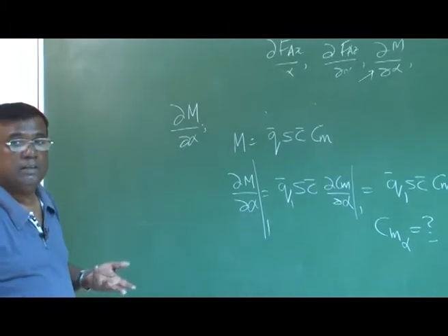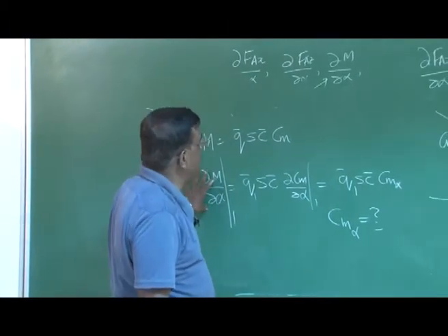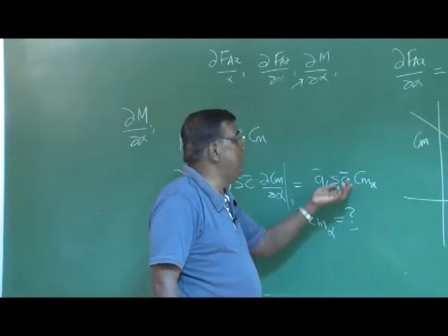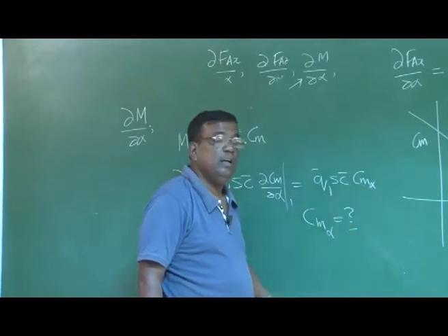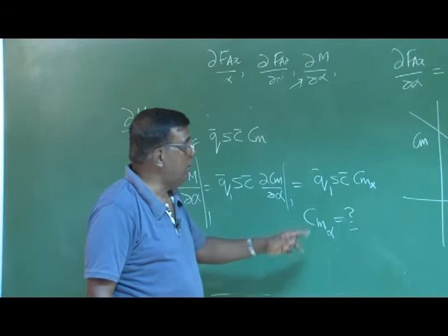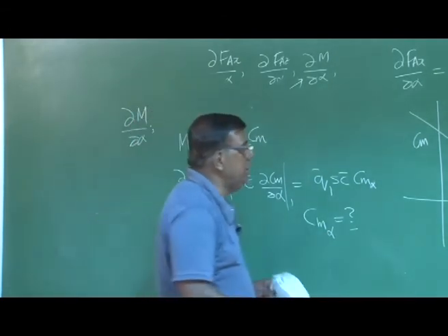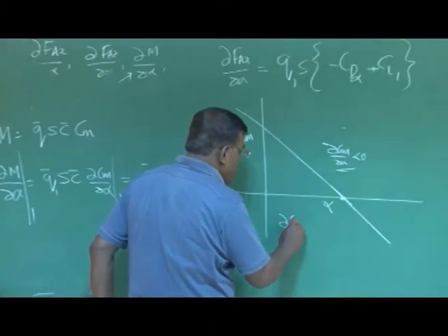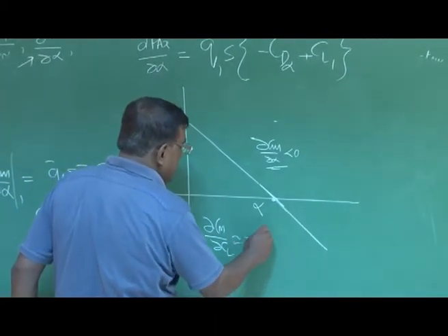Absolutely, from the configuration you can find it out. So again, I know how to calculate dM by d alpha if I know dynamic pressure, area, mean aerodynamic chord, and the derivative Cm alpha, which is also linked to static margin. You remember that, okay? Because roughly dCm by dCL is approximately equal to minus static margin.